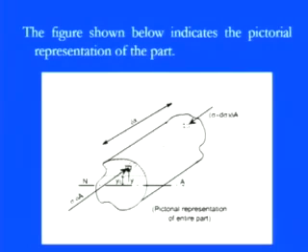You can again visualize those equations from this particular figure. This figure shows a small rectangular cross section, with total length delta x, and the neutral axis passing through it. This is our main strip, on which our focus is how the stresses will play. On one side we have sigma into dA, and on the other side we have sigma plus delta sigma into dA. So you see here how they will balance.